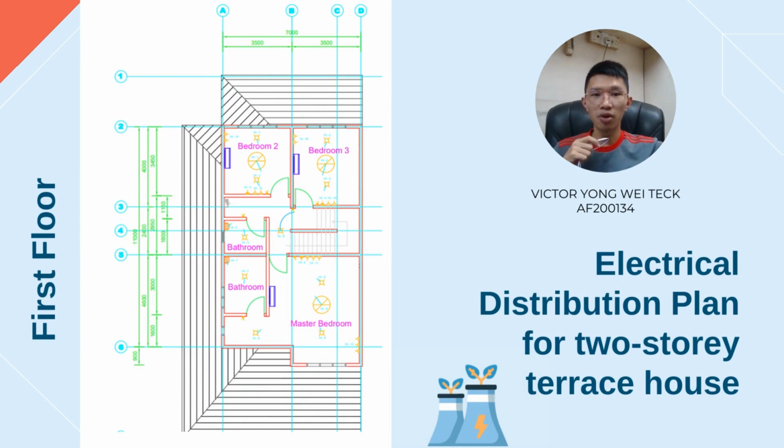On the other hand, this is the first floor electrical distribution plan. It seems like the ground floor electrical distribution plan. It also consists of distribution board, wiring network, lighting, fan, and air condition. On this floor, there are 3 bedrooms that have air conditioning installed. The selection of air conditioning is based on the calculation that we did before, in order to achieve the thermal comfort in the room that is accepted by the occupants.